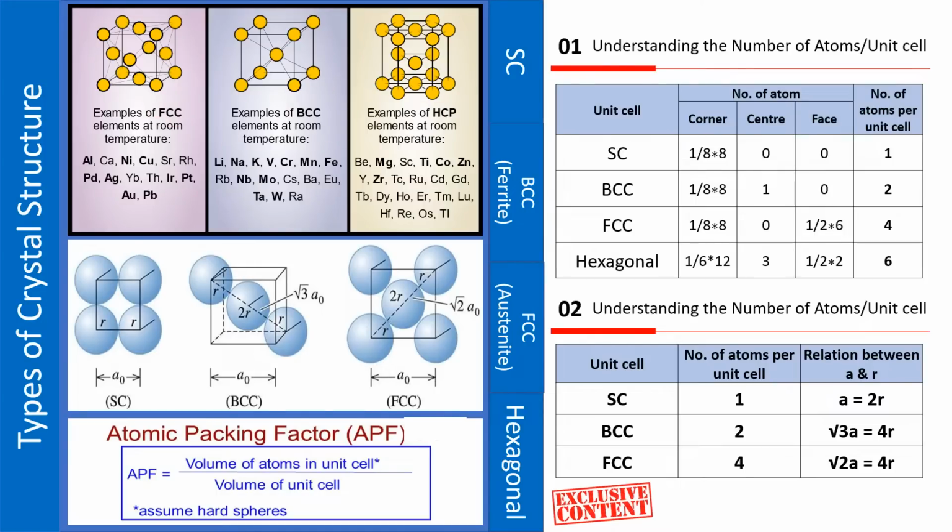First, we need to understand what a lattice is. It is nothing but a pattern of atoms which is there for any type of element. For example, if we talk about aluminium, nickel, copper, we will find that FCC is the basic pattern. For iron, manganese, chromium, we have a BCC structure. For titanium, cobalt, zinc, we will have an HCP structure.